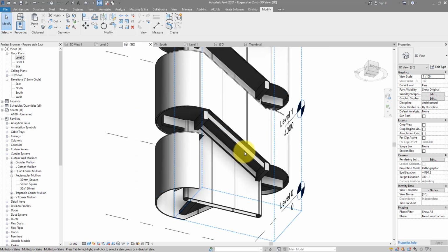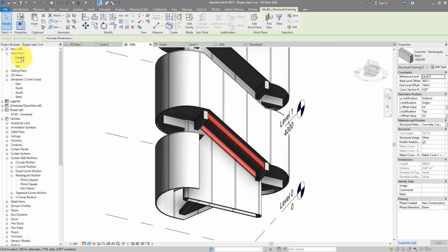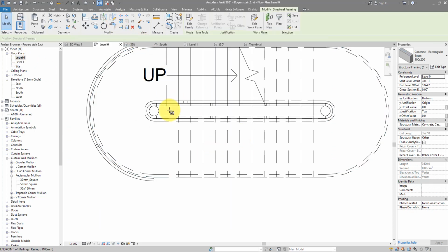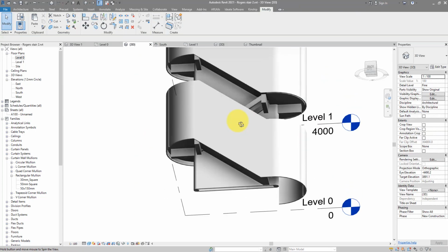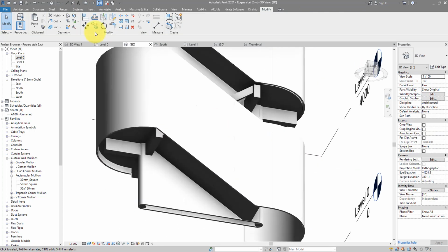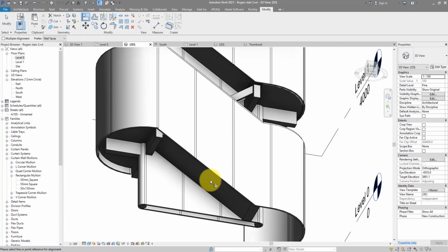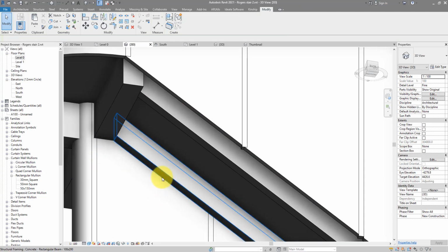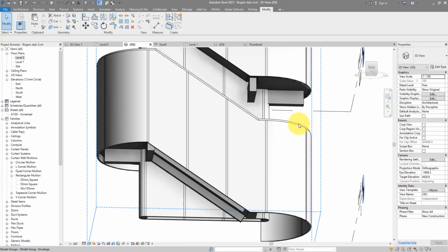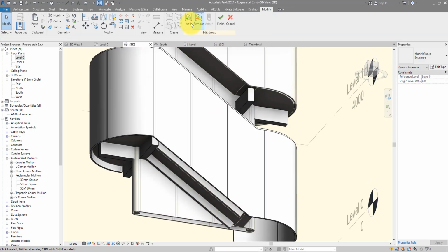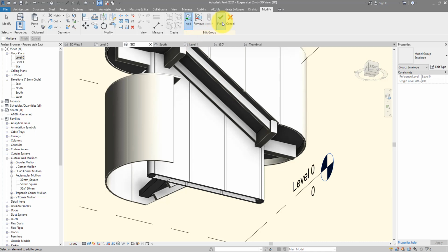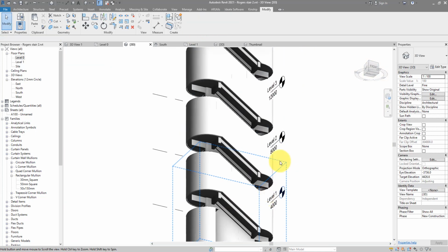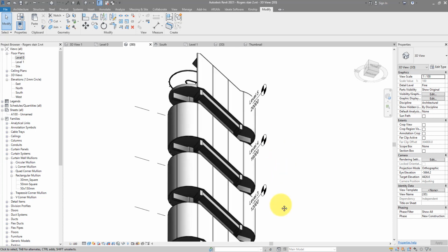We can now select those two smaller beams, go back to plan view, and mirror them to the other side. Over here, it's just a matter of aligning them again to this other sloping plane of the stair's underside. Here we go. I can now select this group and include our new beams into it. Look at that, everything's copied across nicely as well.